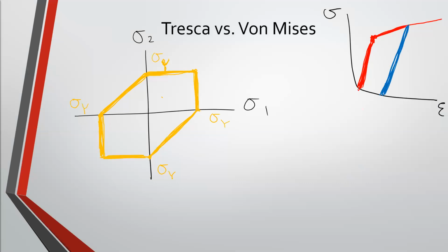So now I can bounce back and forth on this new elastic region. But you'll notice that you keep being elastic past your previous yield stress. Now that you're on this blue curve, you stay elastic until you come back to that point where you left your initial stress strain curve. And so what that means is your yield surface has expanded from here to there. That makes sense?